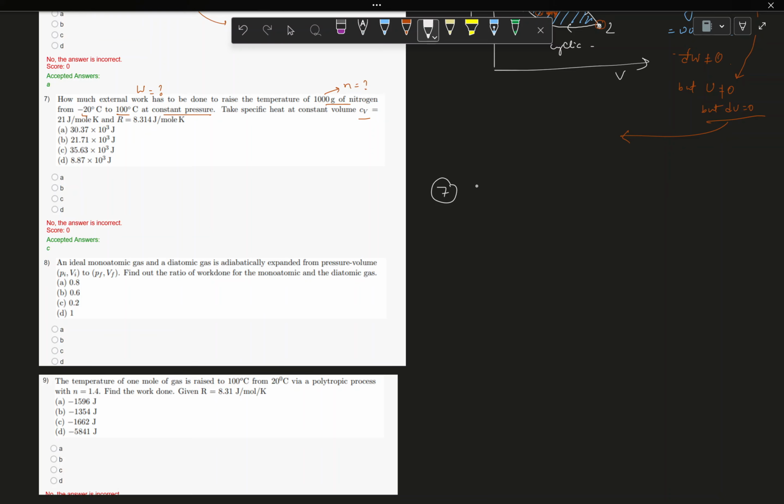So you have to calculate W. You know that the work done is dW equal to pdV, right? Now in this case, because this is an ideal gas, obviously, because if nothing is mentioned we'll assume it is an ideal gas, P is nRT by V dV.